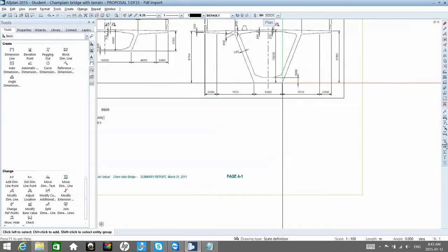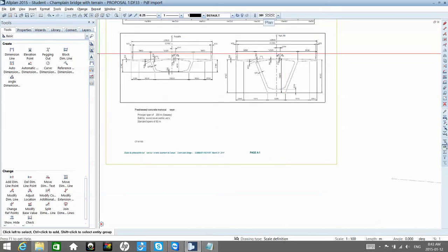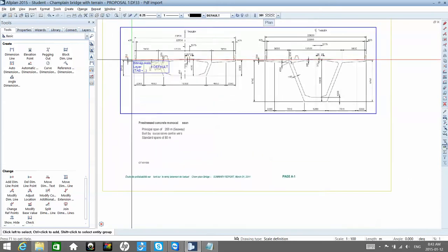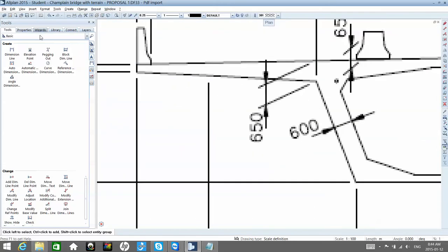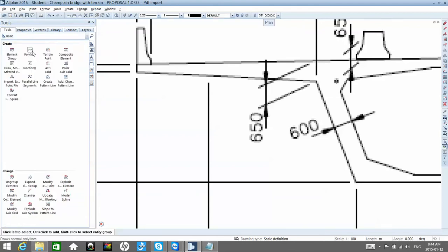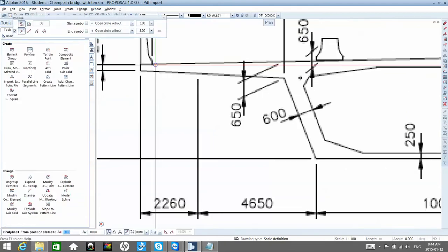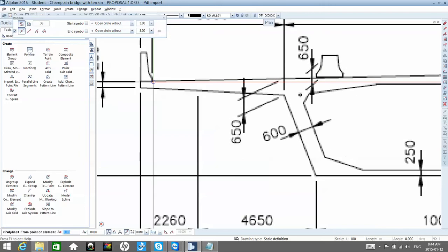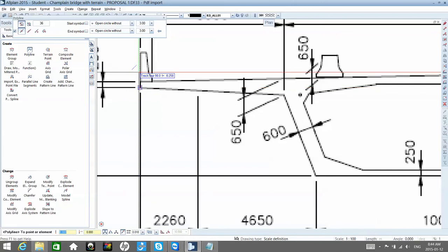We'll calculate this, but first we'll draw the two sections. We've done this before, but I don't know if we have them, and last time one of them had a problem, so I'd prefer we draw them again with this function with polyline. So we'll make sure it's a closed surface.